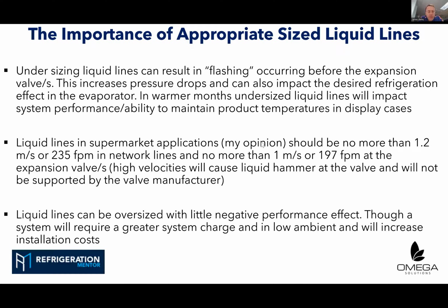Generally, what I've always allowed for in certain parts of the system is a bit of a stub that's capped off and brazed up, which will allow for that future expansion, a couple of K sections. But you're talking much bigger systems than what we have here in the UK. Now, what MicroPipe can do is you can run dual suction lines. So you can run suction lines in parallel with one another. Now, I guess that in itself, you're actually sizing for a specific load, but it's like the reverse of having a riser. Effectively, you can have a series of horizontal pipework, so that would help.